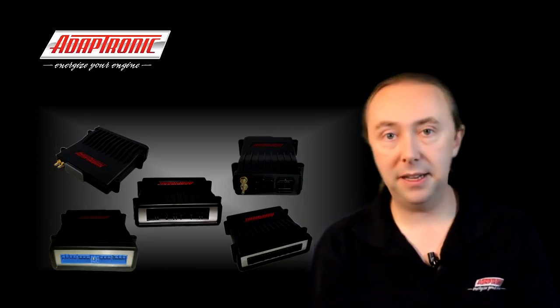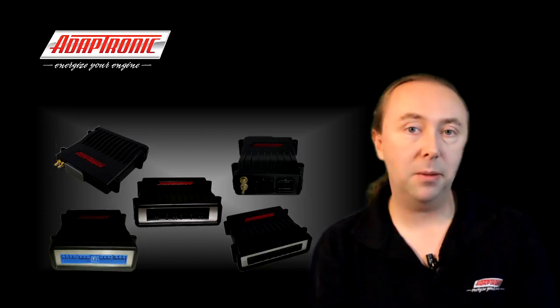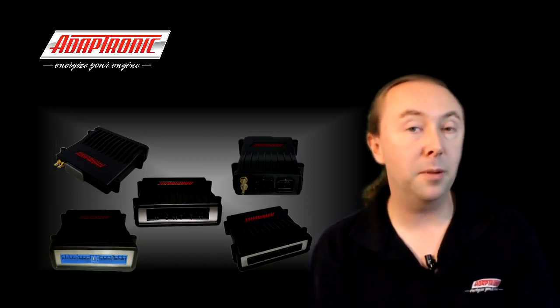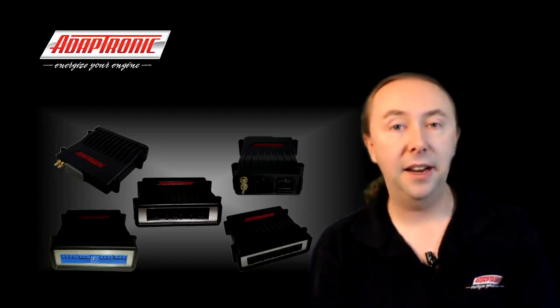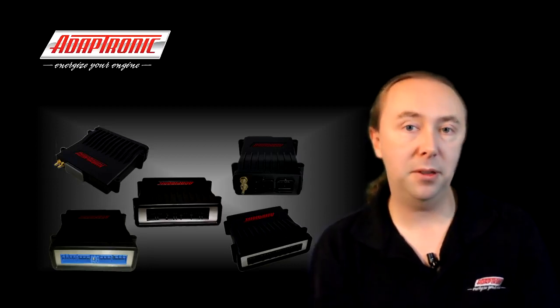Now, this method also applies equally well to external wastegates. The construction of an external wastegate is normally quite different, and you have the bottom port is the one that needs pressure on it to force it to open, and the top port is the reference, if you like, which on a single port configuration will be open to the atmosphere, and on a dual port configuration would be the one that gets switched between atmosphere and boost pressure.